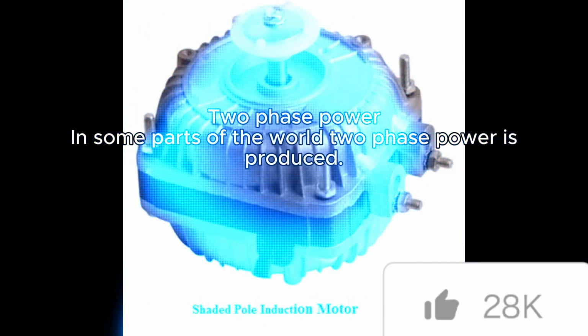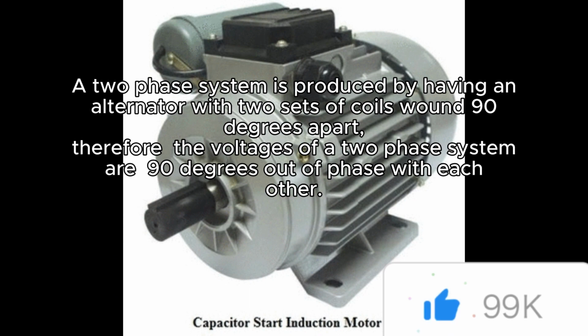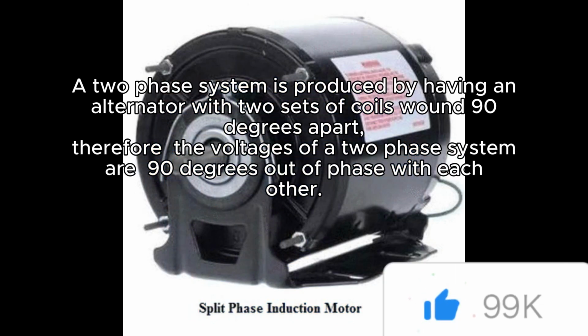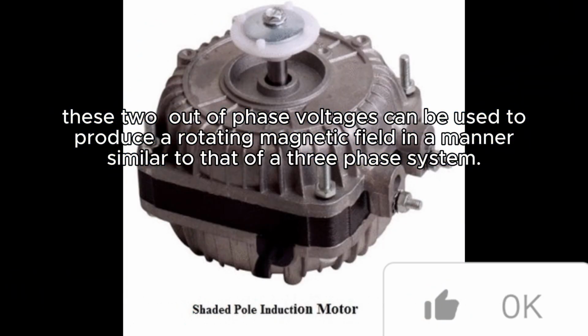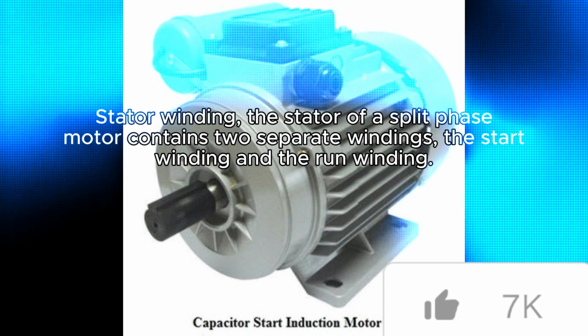Two-phase power. In some parts of the world, two-phase power is produced. A two-phase system is produced by having an alternator with two sets of coils wound 90 degrees apart. Therefore, the voltages of a two-phase system are 90 degrees out of phase with each other. These two out-of-phase voltages can be used to produce a rotating magnetic field in a manner similar to that of a three-phase system.